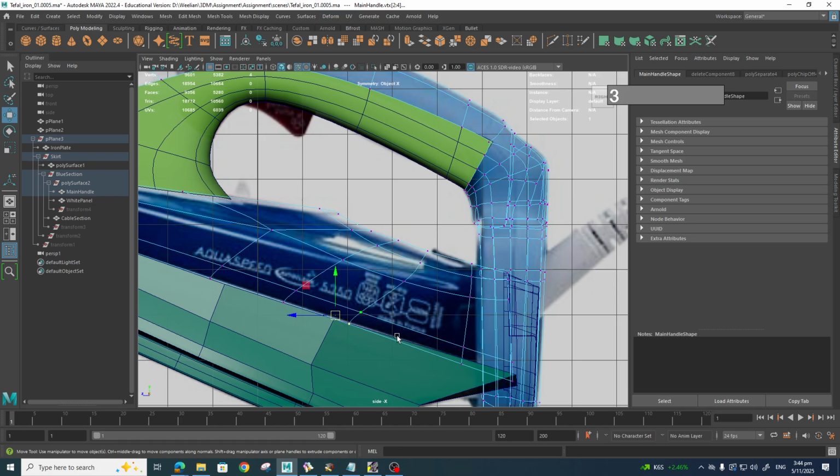Okay, we can use the sliding tool to slide it back. These two as well. We'll slide this back here. Let's slide this back slightly. Just spread them out. You do not want to have too many of the vertices bunched up together.